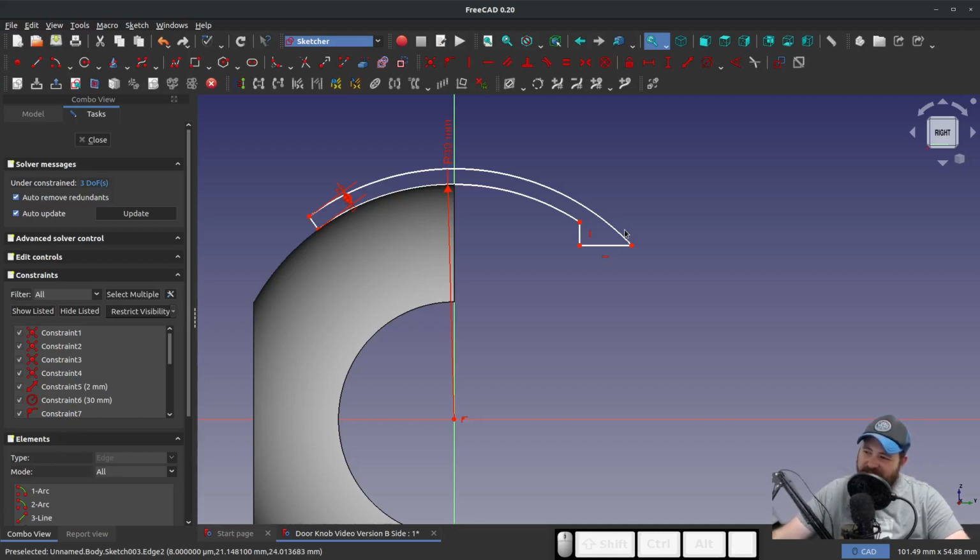And from your yield strain, you take 70% of that value, and that's the maximum you want to have your snap flex. You never want to have a snap stuck in a stressed position. You always want it to be held in a neutral position after it's snapped. So neutral position, you go to snap it, goes to 70% of the yield strain max, and then it snaps back into a completely relaxed position. And that's the ideal snap.